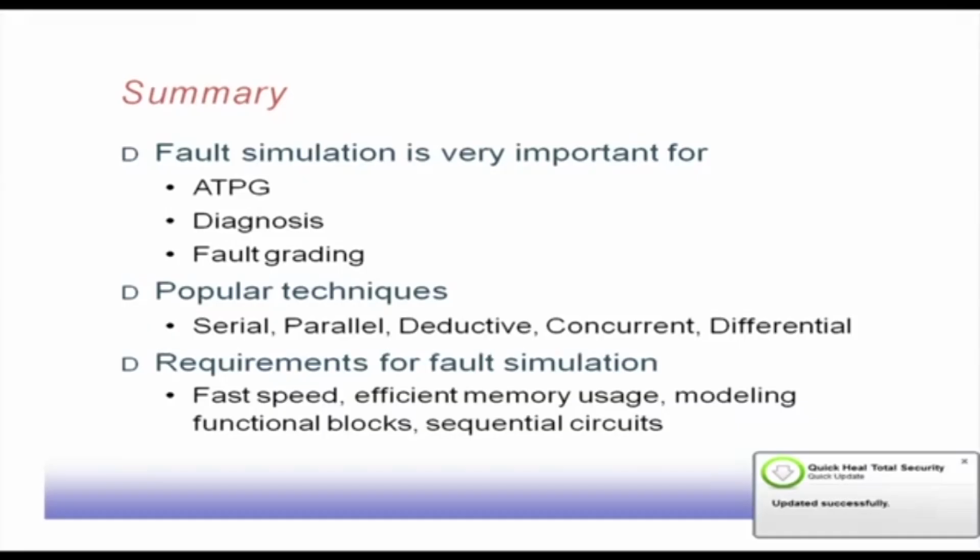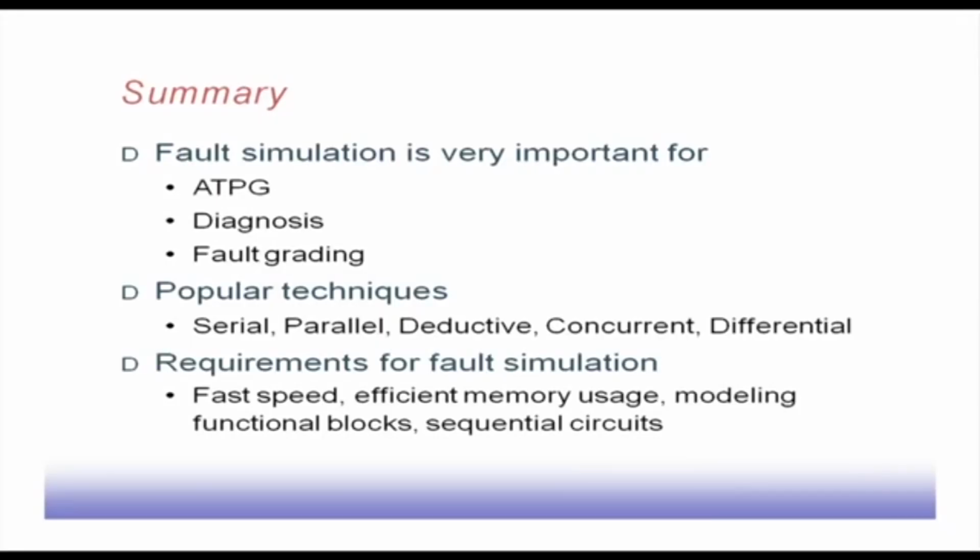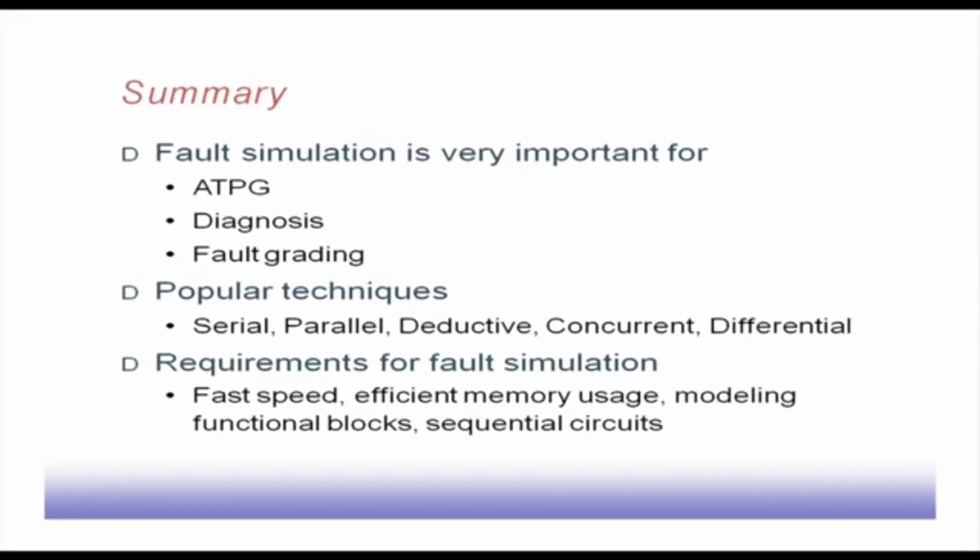So, to summarize, fault simulation is very important from many angles, like ATPG. If you are trying to develop some automated test pattern generation algorithm, we need to see the faults that are already covered by the generated test set, and then we try to augment it by generating further test patterns. So, ATPG algorithms very much need fault simulation. For diagnosis purposes, we need to know all the faults detected by a particular pattern. So, we need to identify all those faults, and there also fault simulation is important.